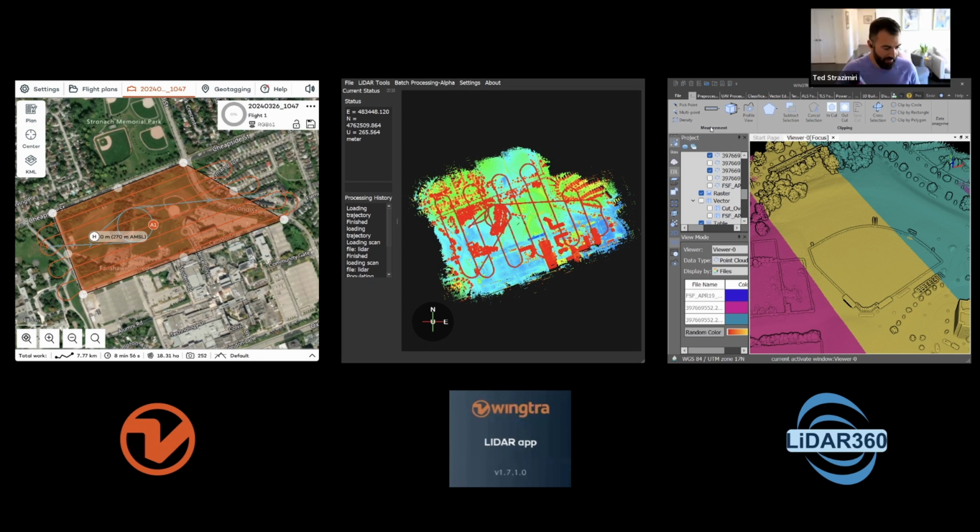Yeah, approximately. You can see here that the RGB flight, the RGB 61, the one that I have on the left hand there, I built that to see what the difference would be between the RGB 61 and the RX1R. I actually used the RX1R. That's the one that I was given. So lower resolution, more overlap, and I shot the RGB at a centimeter GSD. And also, it was the day before the LiDAR flight occurred, and the wind conditions were a little bit different. So you can see that the direction of the flight was different because of that.